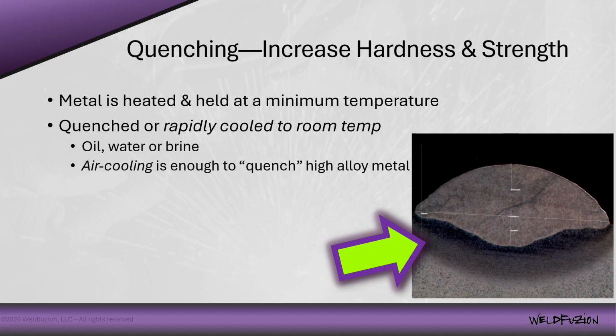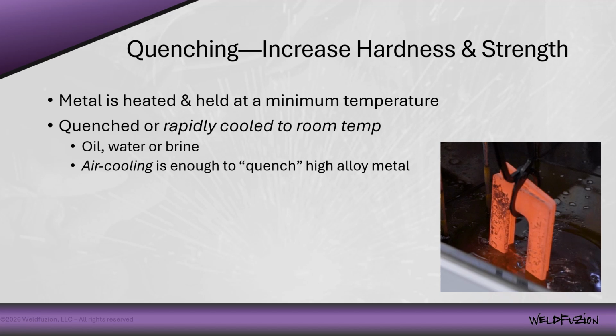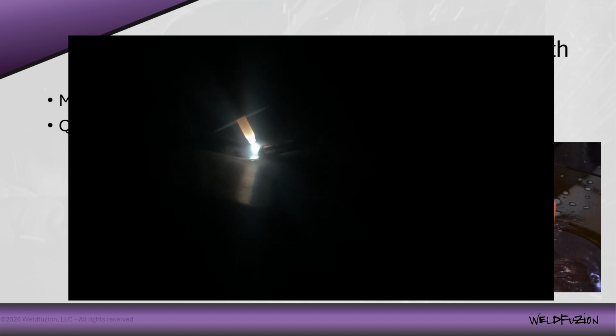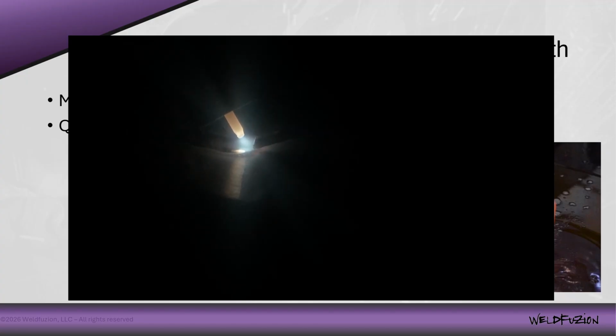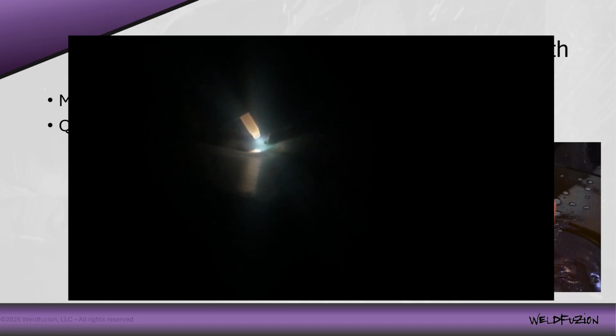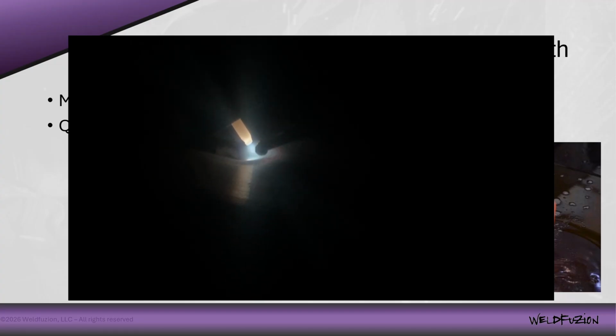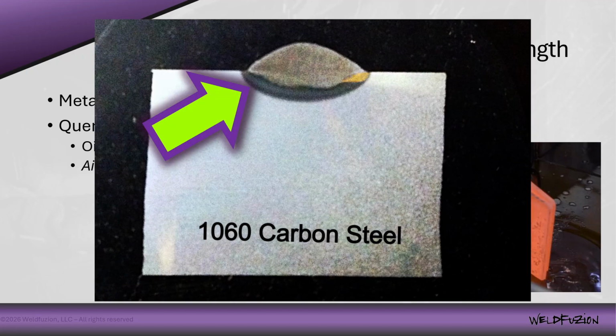This is the primary concern when we're welding such metals because welding generates temperatures at and above the recrystallization temperature, right? We're melting the metal. So that means around the area that we melted, that's going to get super hot and recrystallize in a very localized area, which is kind of the whole issue with the heat affected zone. It is not homogeneous, it's not evenly distributed out through the metal, right? It's going to be right there, concentrated in and around and under the weld bead.